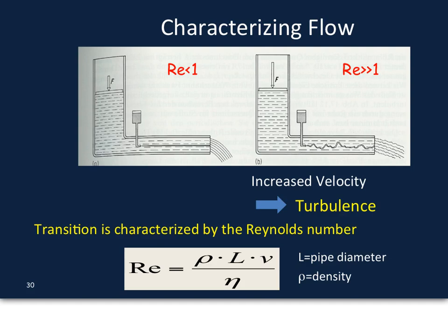And in microfluidic devices, we have what are called low Reynolds numbers. So these are Reynolds numbers that are less than about 1. The Reynolds number is used to characterize how turbulent flow is, and it's given by rho, the density of a given liquid, its viscosity eta, the diameter of a given pipe through which the fluid is flowing, and then the velocity of the flow.